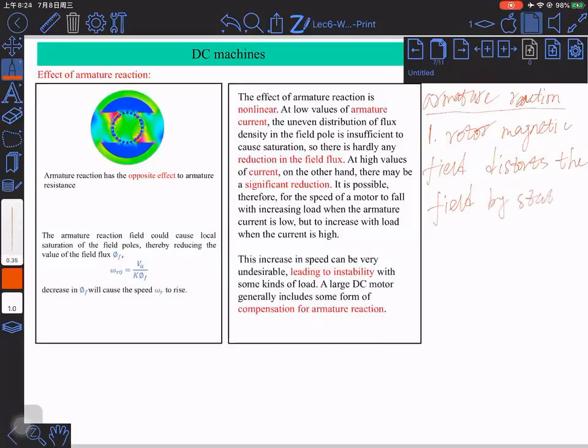The consequence is that when the conductors rotate to this vertical surface here, which is perpendicular to the flux linkage, we have the flux linkage not 0. Because of this, we have an electromotive force developed which is not 0, over the very small internal resistance. Why? Because at this vertical position, the commutators short circuit both the internal and external circuit.